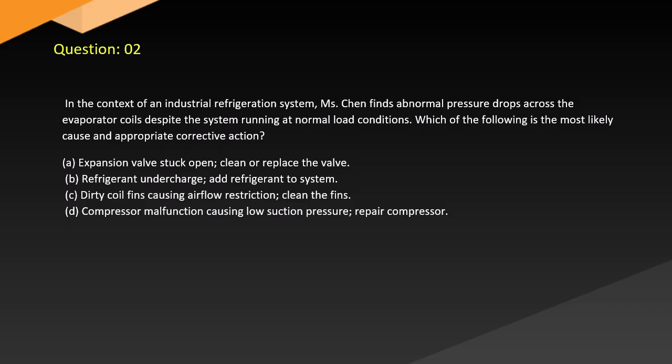A. Expansion valve stuck open. Clean or replace the valve. B. Refrigerant undercharge. Add refrigerant to system. C. Dirty coil fins causing airflow restriction. Clean the fins. D. Compressor malfunction causing low suction pressure. Repair compressor.